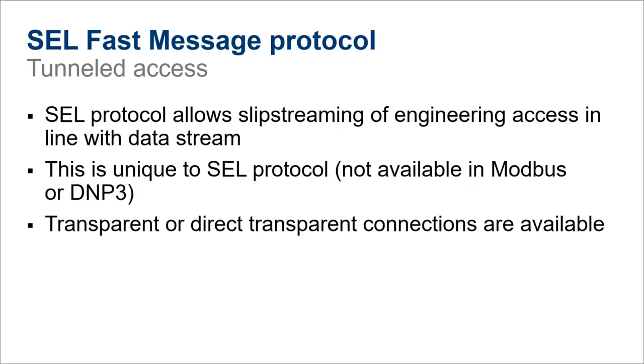SEL fast message protocol also allows for something that we call engineering access. This allows you to have a connection through a single serial connection that is transmitting both data to SCADA and also terminal data to an engineer. This is unique to SEL protocol. Modbus and DNP3 don't support anything like this.